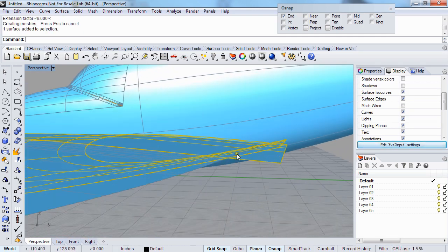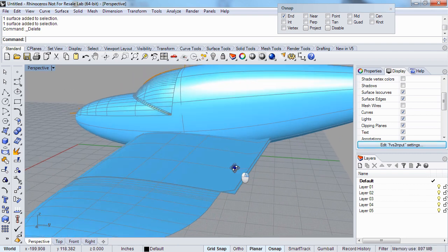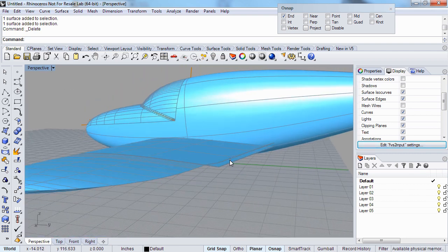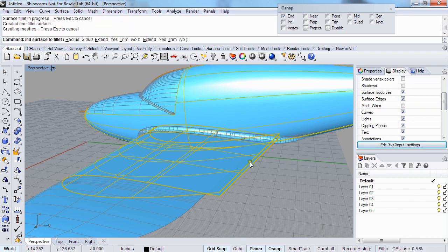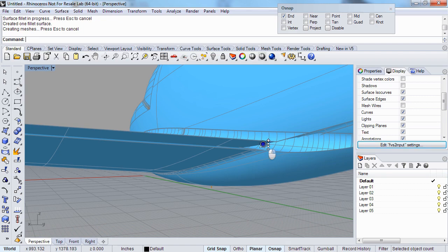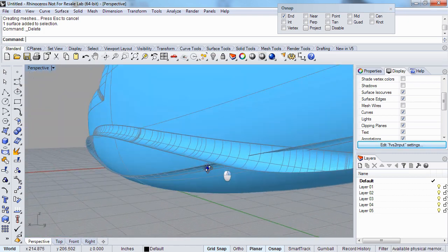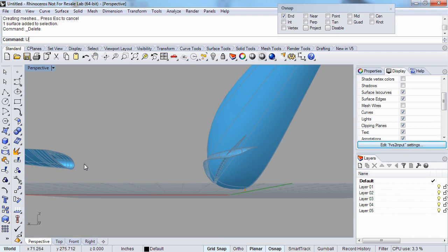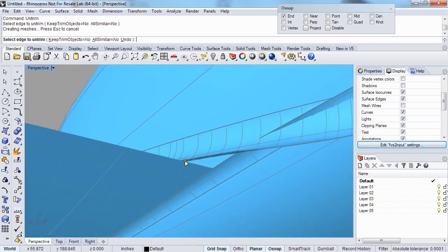There we go. So now what I've got is a wing surface that folds over on itself here and extends further than what I need in the final thing, but it's kind of a dummy surface that I need to get the fillets right. So let's see what we get here. Fillet surface, and lined up here. Of course, who knows? This could still not work because the shape isn't quite right, but now it looks like it might have worked. But now I've got, let me take that, untrim that. So now I've got a fillet, wraps around there.